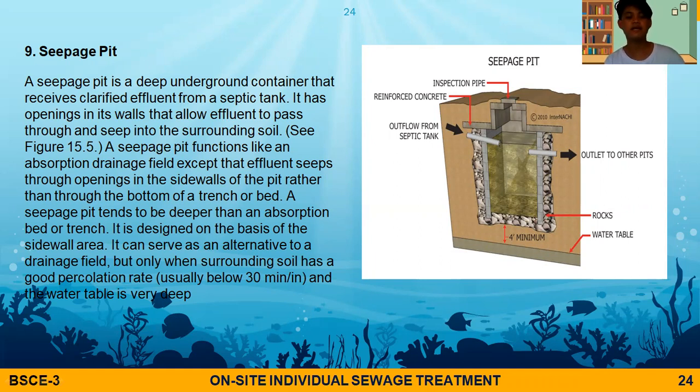It can serve as an alternative to a drainage field, but only when the surrounding soil has a good percolation rate, usually below 30 minutes per inch, and the water table is very deep.